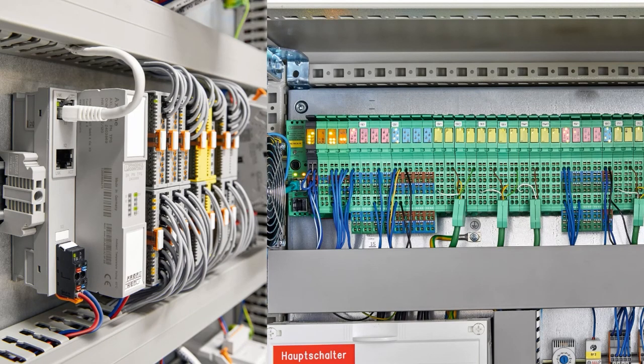The first I/O modules, when the distributed I/O module was invented, it was always a block of I/O. You had a big block. It had 16 inputs and 16 outputs. You'd install it in your machine, and immediately you start wiring it up, and you realize, I need 17 inputs. Now what do you do? Now you buy another block with 16 in and 16 out. For one, that didn't make sense. So a modularity concept was really key and focused in the I/O market.